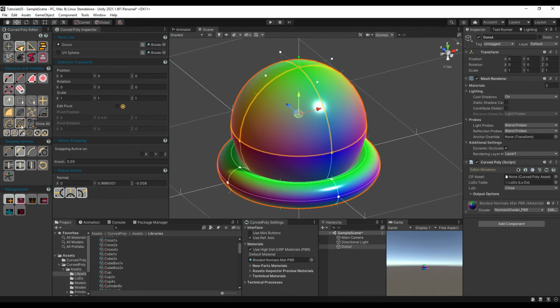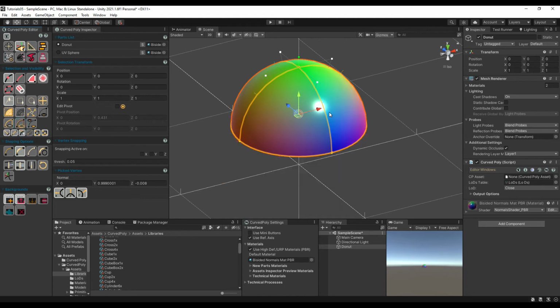There is also the opposite workflow. We can select a group of elements we still want to see, and hide everything else. This can be done by pressing on Hide Unselected. Again, when we want to restore elements which were hidden, we need to click on Show All.